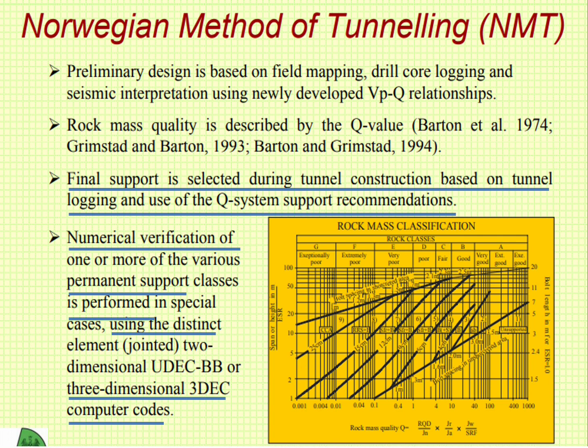Numerical verification of one or more of the various permanent support classes is performed in special cases. Using the distinct element jointed two-dimensional UDEC-BB or three-dimensional 3DEC computer codes is rarely resorted to for numerical verification. Mostly the design supports in the Norwegian method would come from this graph, which has parameters of Q and the span of the opening.